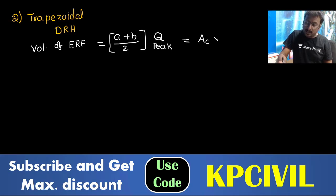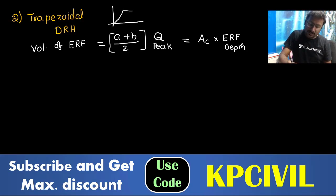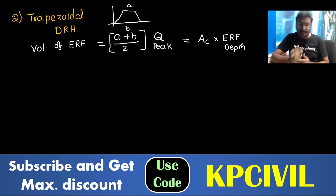Again that is equal to area of catchment into effective rainfall depth. We can equalize the volume of effective rainfall with respect to the trapezoidal direct runoff hydrograph. This is A, this is B. You can take it now: (A plus B) by 2 into peak discharge equals area of catchment into effective rainfall depth for the trapezoidal DRH.